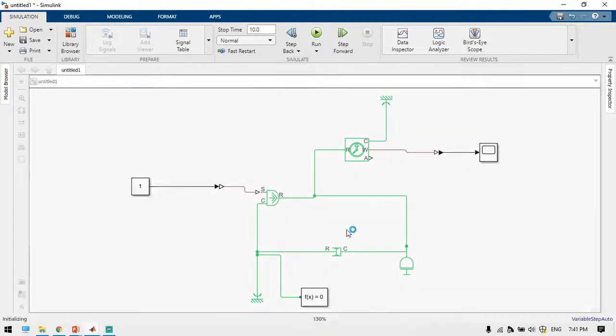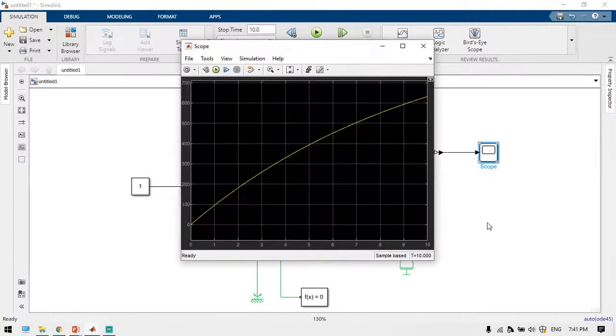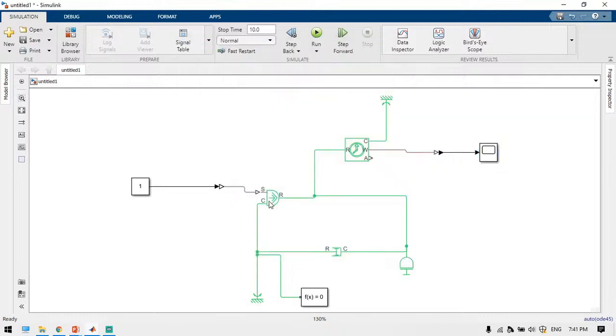Similarly, we have to add the additional blocks, the speed increaser and speed decreaser. See here, we just applied a torque source, so it has generated. Then the system runs and generates the velocity in radians per second. That is the angular velocity of the system. Like this, we can sense the particular value called omega. Like that, we can measure the torque also.